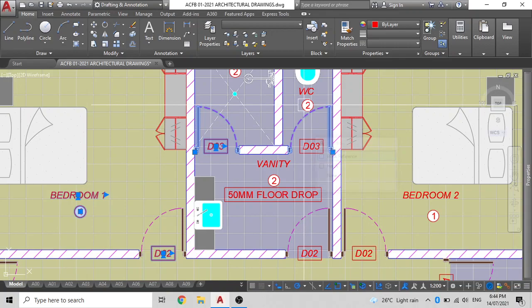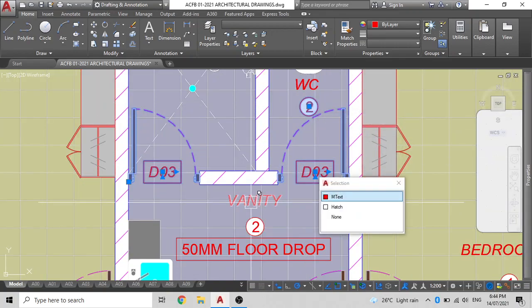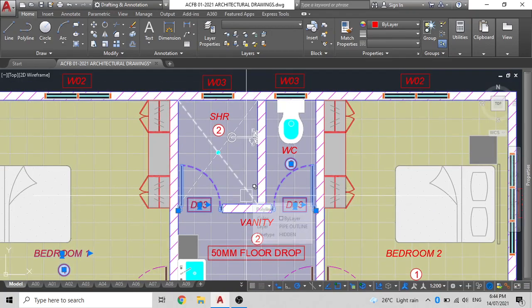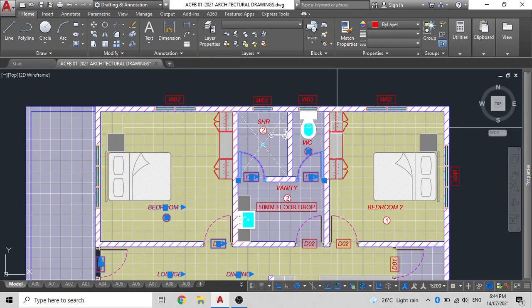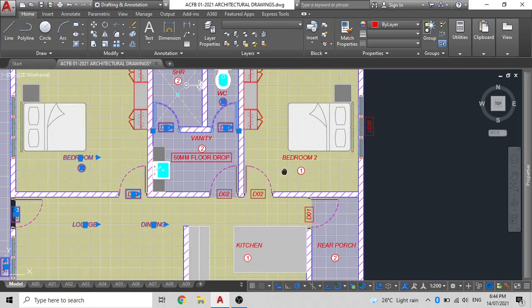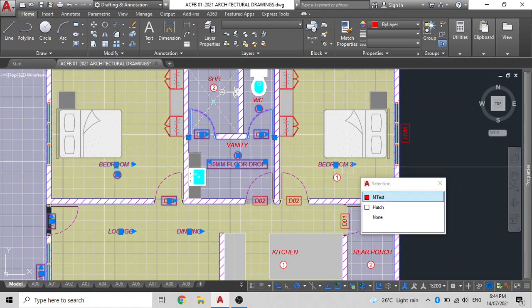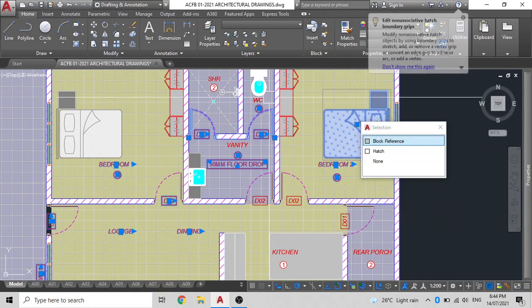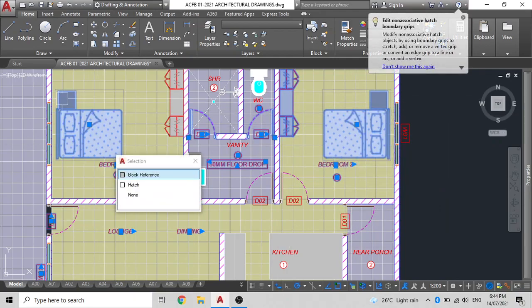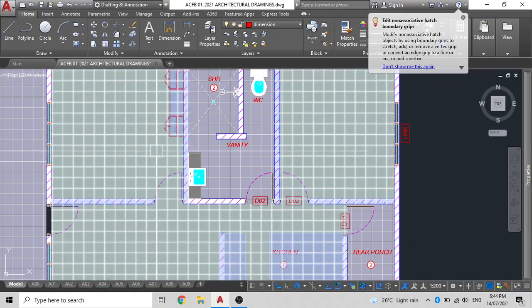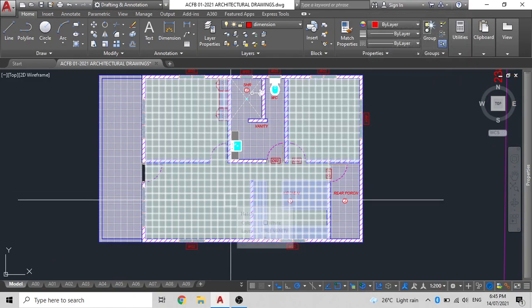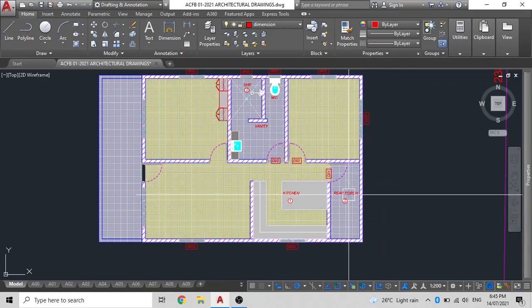You can leave the shower fall and the other things because those are important. This is the plan that is going to show where you're going to drain out all your shower and other wastes. You can remove these things. You can also remove all the blocks because these are unnecessary in a side plan. Or you can create separate layers for everyone. Let's say you can say side plane joinery, and you can just turn off your side plane joinery. So this will not turn off other things.